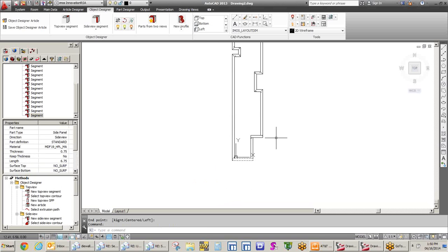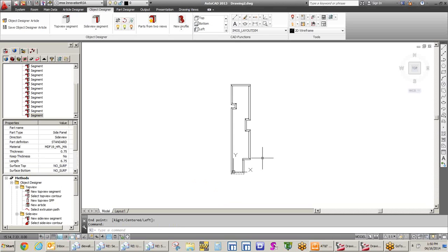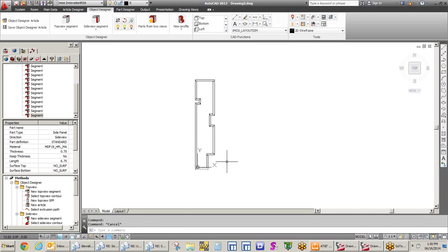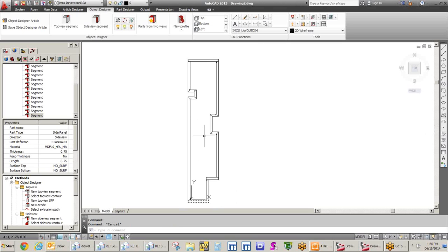So really the only thing that I'm doing is creating the panels that are going to be extruded along any kind of a shape. In this particular case, I'm going to use an AutoCAD command called boundary, and I'm just going to pick inside of this to generate a polyline. Otherwise I could have easily just traced around any of these that I want to work with. And in this case I do actually want to do that.